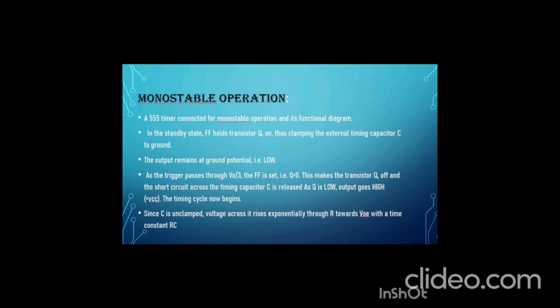In the steady state, the flip-flop holds transistor Q1 on, clamping the external timing capacitor C to ground. The output remains at ground potential, that is low.